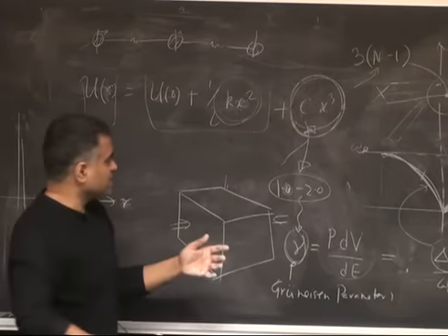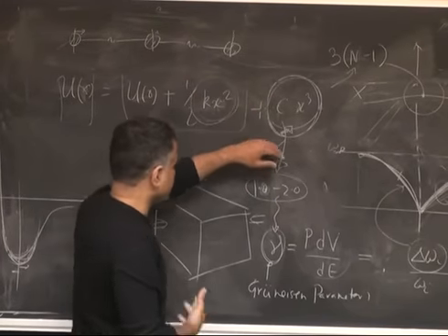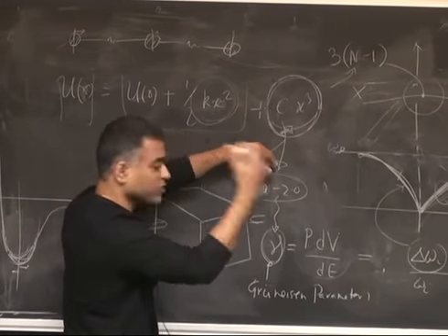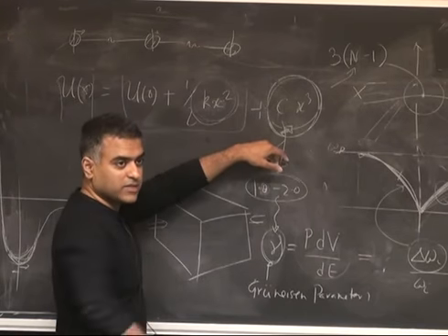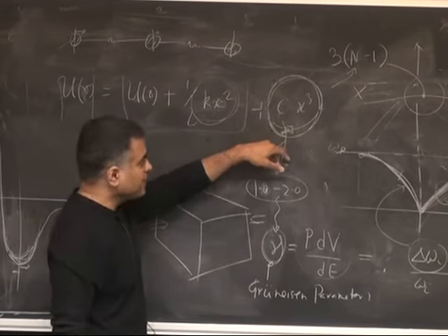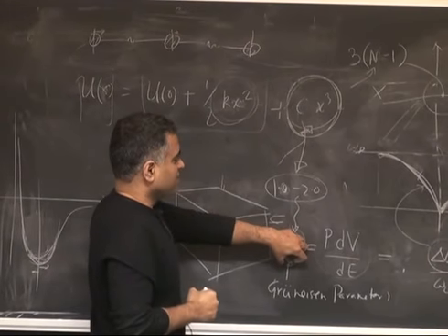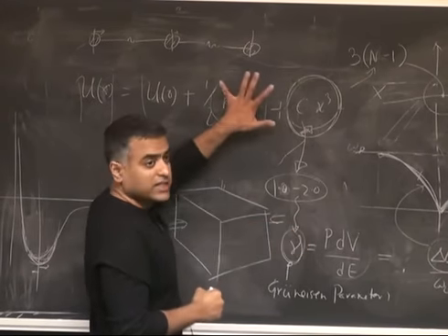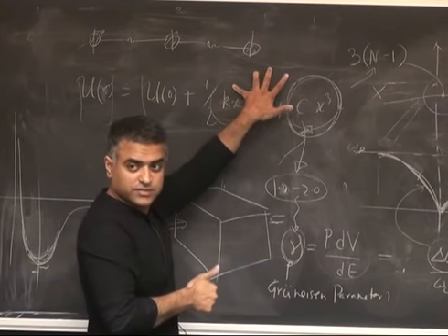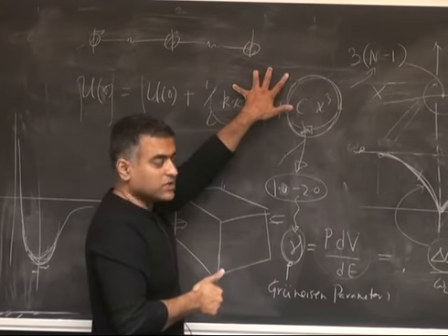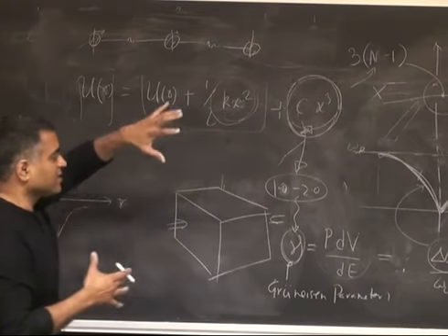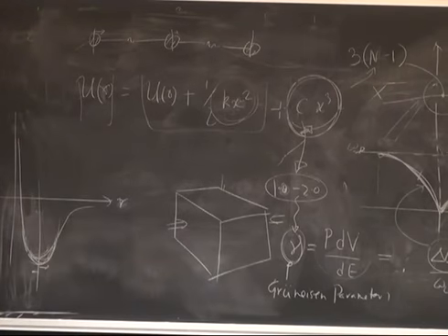Because the most perfect crystal is when you don't have anharmonic terms, lattice waves can keep going. There is nothing to scatter, right? And my thermal conductivity is infinite. That means if I have a small Grüneisen parameter, it's closer to the ideal. So I'll have a higher thermal conductivity, right? The crystals that are much stiffer will have a higher thermal conductivity.